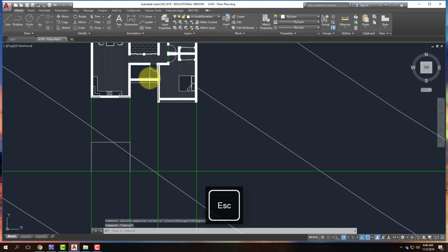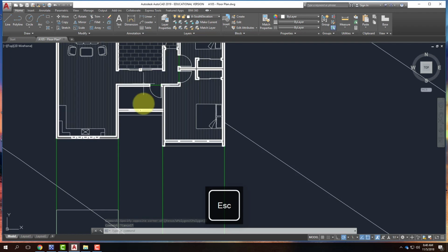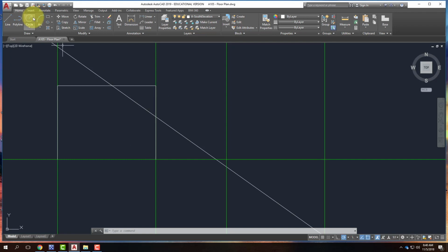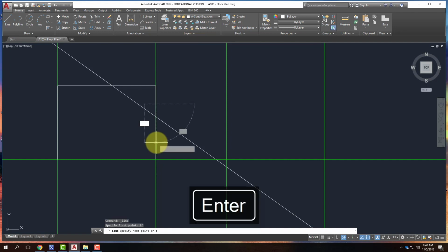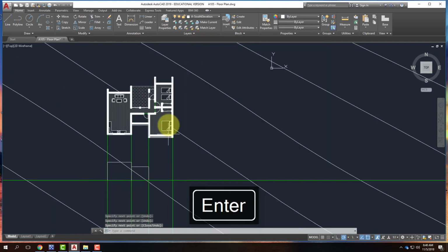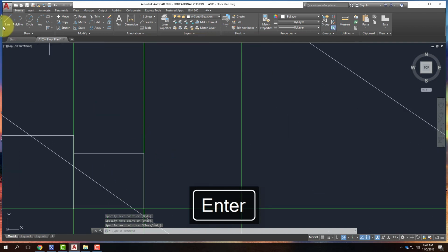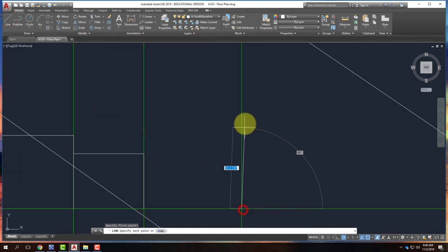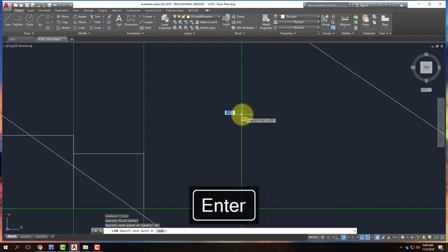Then it steps back into this part, the little bridge of my building, in between this wing and that wing. And so when I draw that, I want that to be a little bit shorter. So I might come up to maybe 9 feet here. So you could start here, or I could use my tracking and come up 9 feet, draw over to right there, and draw back down, like that. This last piece is going to be a little bit taller, so it would be 16 feet. So I'll start here. I'll go up to 16 feet. I'll go over, and I'll come back down.